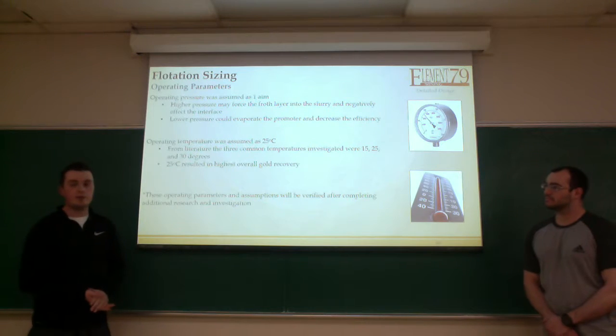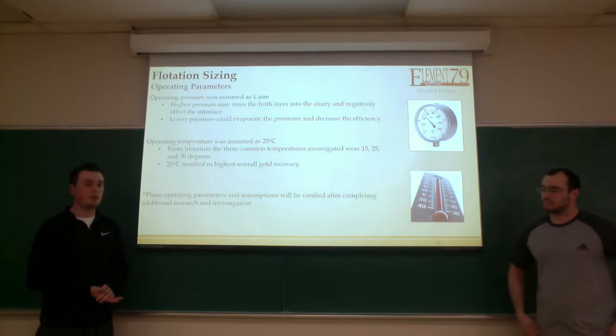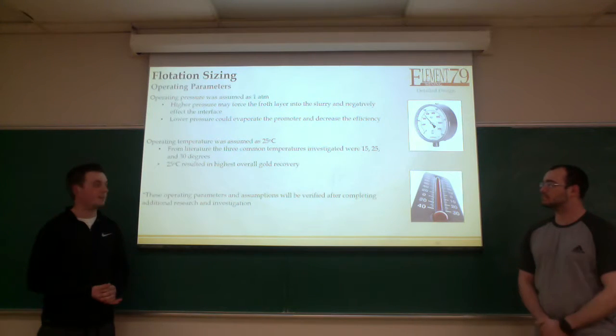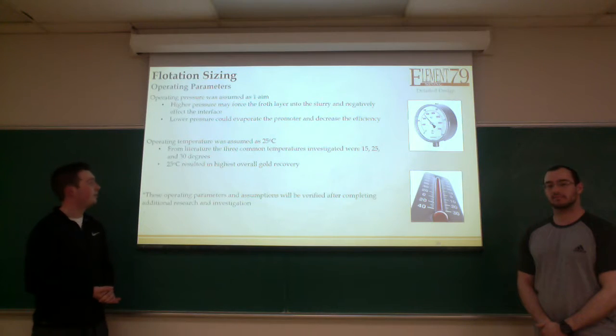And finally, we determined our operating parameters for our flotation cells. We found that our operating pressure would be 1 atm, along with a constant temperature of around 25 degrees, so room temperature would give us our best yield.